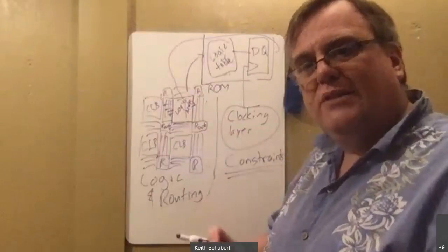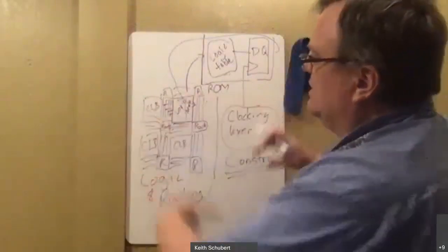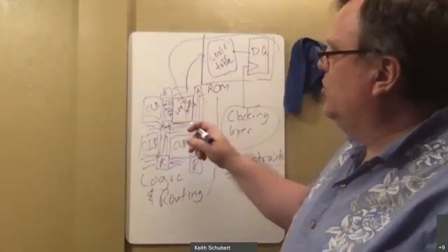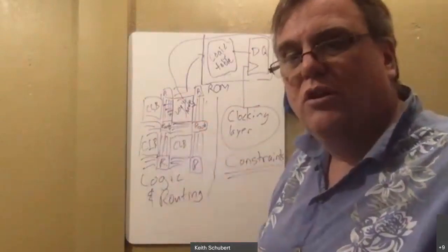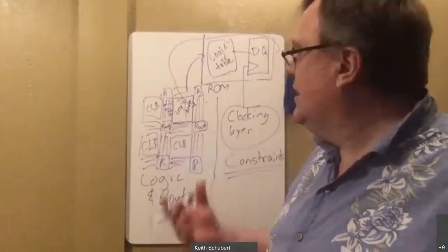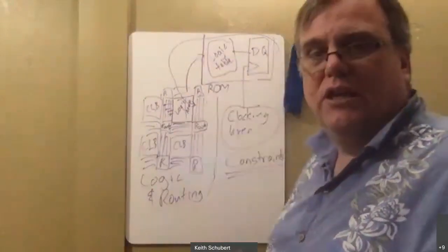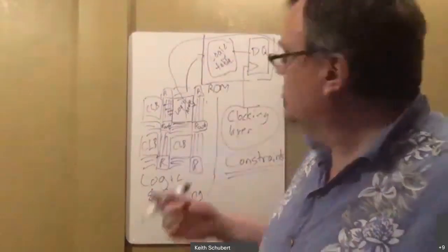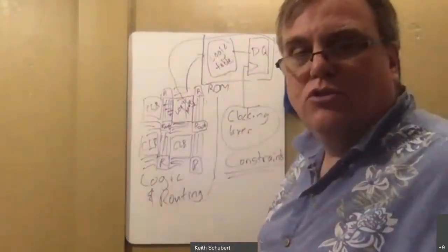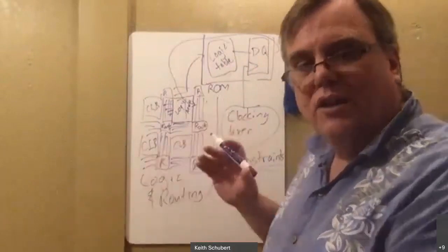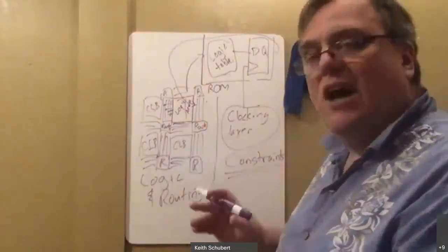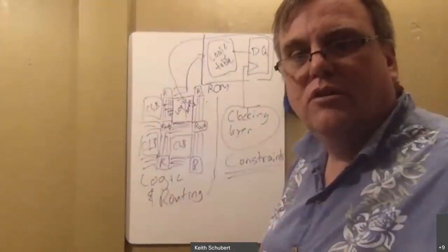When you get that huge mess happening in one area, it kind of expands out to deal with that, which means the routes become longer and the timing becomes worse. So the worse the timing becomes, because it can't do it efficiently, because the clock input is being used for a logic signal, essentially the design grows big enough that the timing constraints aren't met.